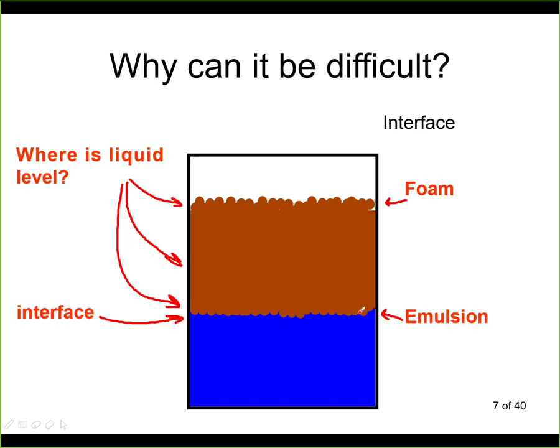And we'll see also some sensors are suitable to give you not only the liquid level, which is here, but they will also give you the interface between the two materials. If you were to use a sensor like ultrasonic, for example, then if we don't have the foam on top, it might be possible, but it will give you only the first liquid level, so the liquid level here of the oil, but it will not give you the interface.